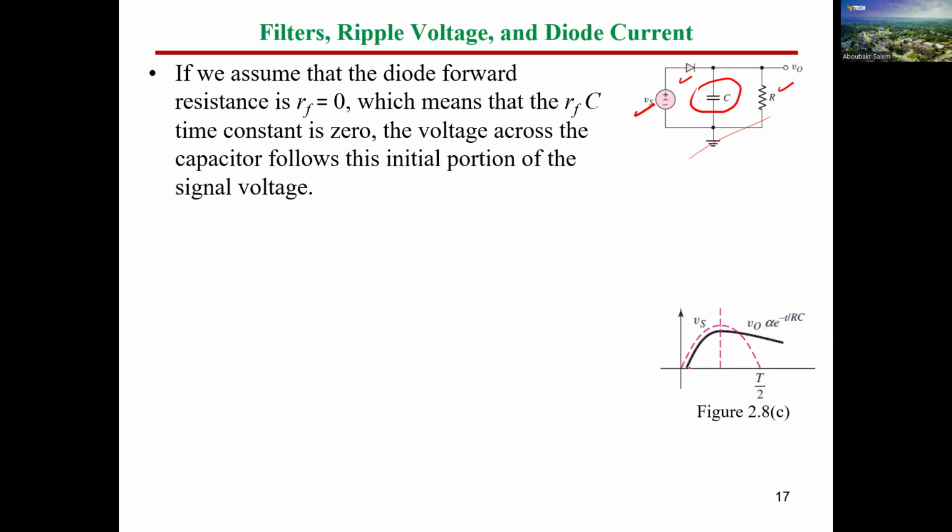So as you can see, this is going to be the capacitor volt here. For sure, it should be less by the value of V gamma. This will be valid until reaching the peak value here. Then let's see what happens if the diode is turned off.